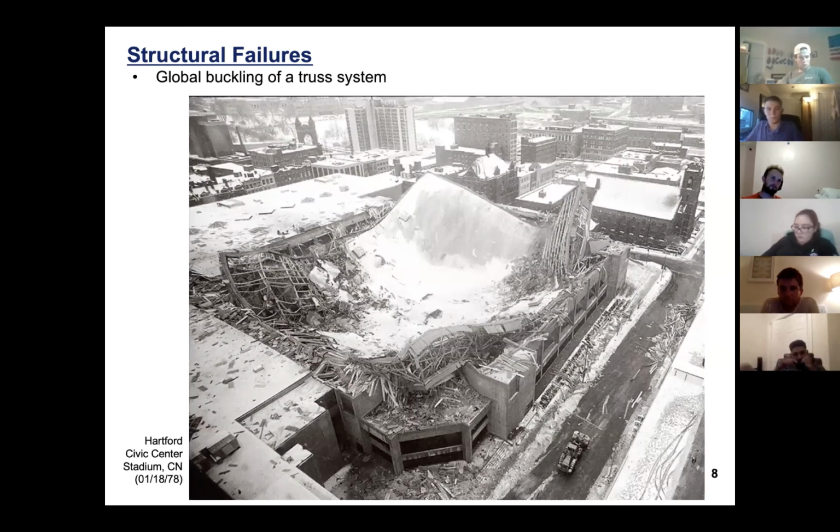Buckling can occur not only to members, but also to structures. And this kind of failure today we call colossal failures, because buckling means a sudden drop of the bearing capacity. And if a structure system lacks sufficient redundancies, once a critical member buckles, it will lead to the total failure of the structure.